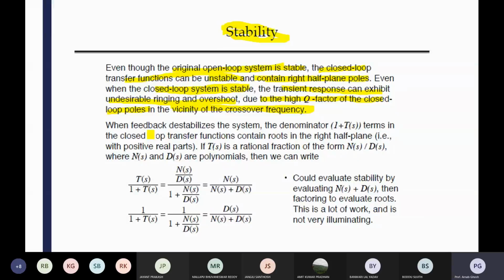Everything is not in your hand, but switching frequency and some other points are. So to control those oscillations and maintain stability, you have to think about a suitable compensator or control circuit. You have to decide which type of controller you are going to use for the design.